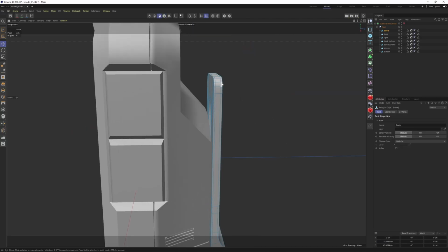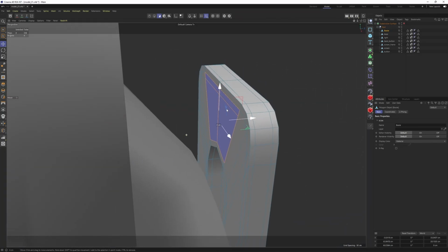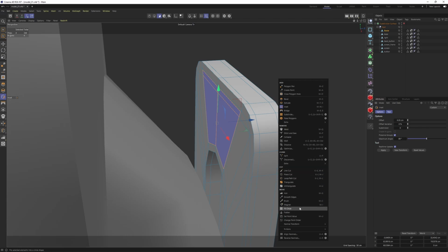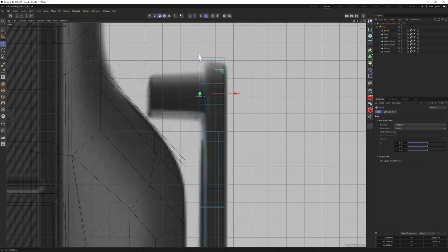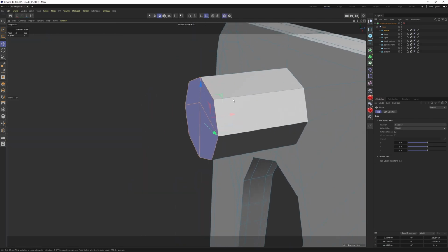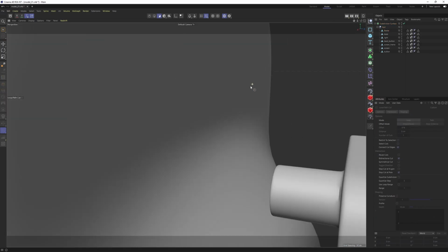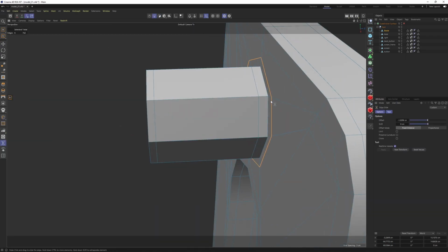It's not over yet. We need to add some smaller details, such as this one. I'm gonna select these 4 polygons so that I'm gonna get more resolution on this one. Then I will make an inset, very small. Select, right click, select fit circle tool. Let's see, yeah, something like that. Then hold down control, extrude. Let's follow that. Make an inset, another loop cut. Here, let's hit Q. I'm gonna make a loop selection and extrude these with slide tool.